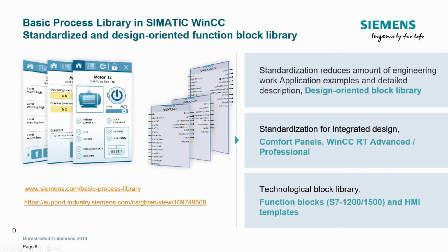So it pre-filters the alarms to just these elements. You've also got setup elements on there as well, so you can decide how it's going to operate, whether you have an external trip fault, for example. And then finally, of course, built into the block as well is the security. So you've got the user access.